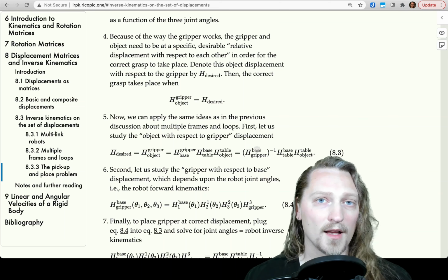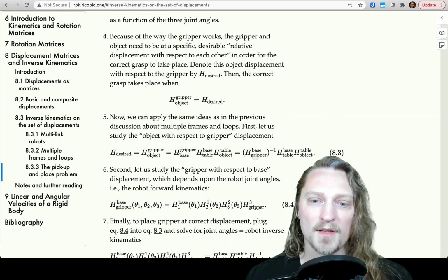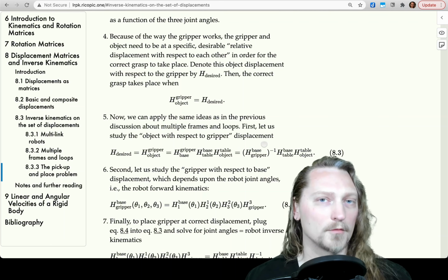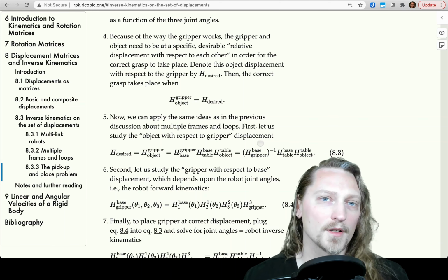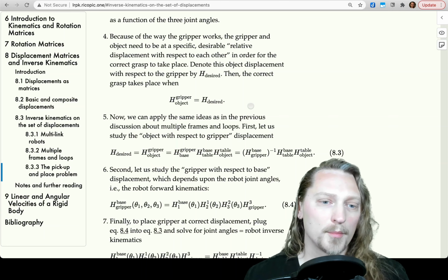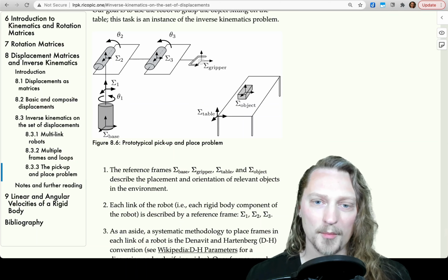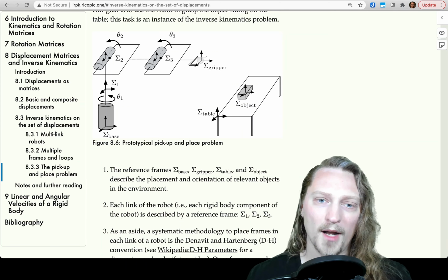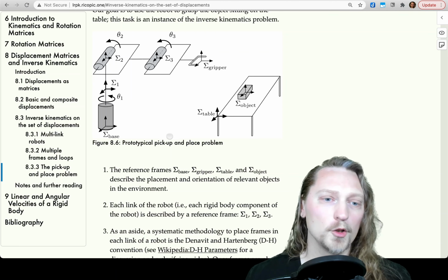And the reason we've done this last inverse here, because this previous expression was also true, is that the gripper base relationship we know usually in this order. The relationship of the gripper in terms of the base and not the reverse. So what we know now is the object gripper relationship, okay? The object gripper relationship is gripper object. So we went around from gripper and base and table and object. We did that sort of part of the loop, if you will.